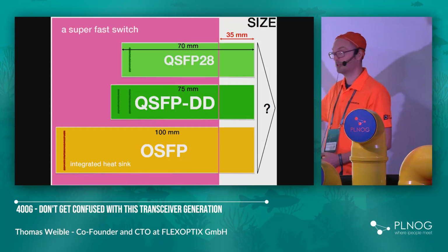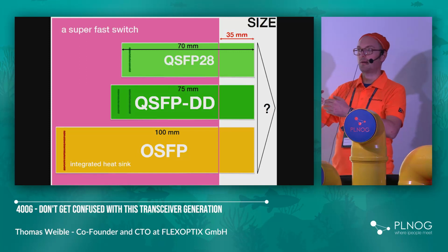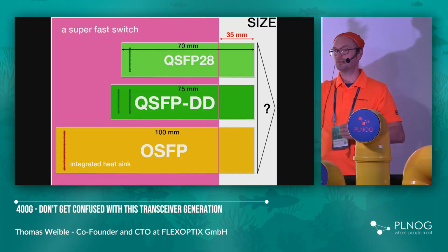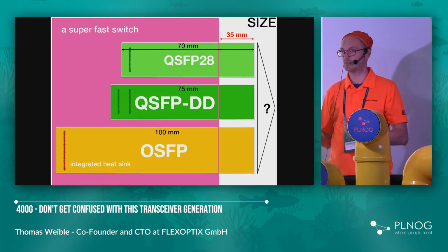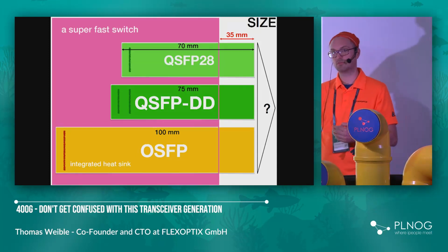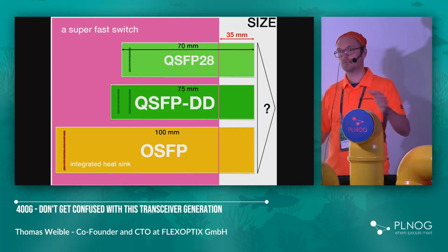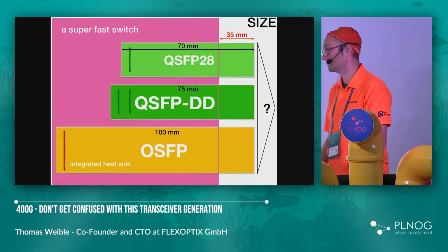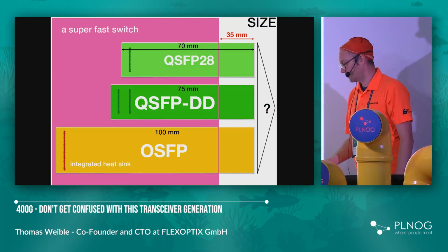That's a critical question because you also need to be aware of the depth to your second rack unit, and then you need a little bit of space also for the AC or DC powering and wiring, and then you might end up with the question, hey, is a 1000 millimeter rack still sufficient, or do we just jump to 1200 millimeters, because that's where we are at the critical mass when you do all the math from the front door back to the back door. What will come here on the connection side, that's what I'm going to show next.